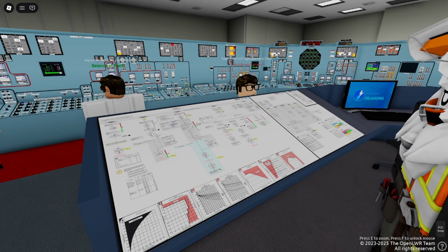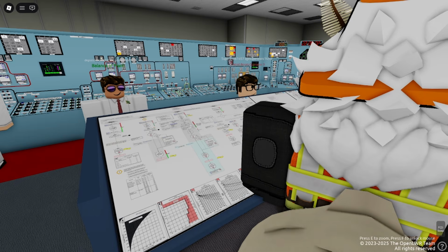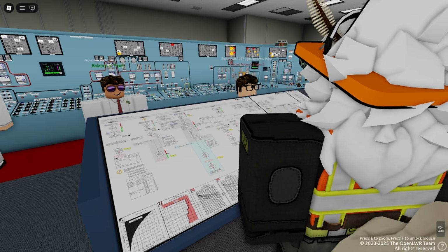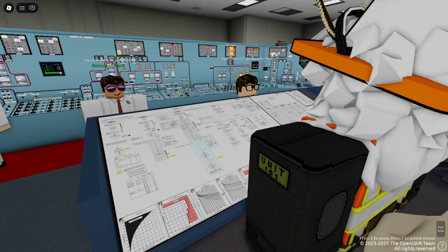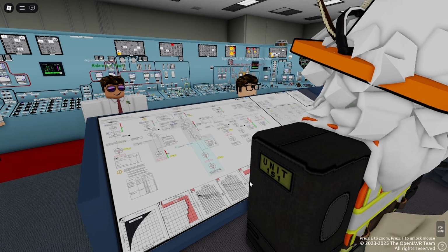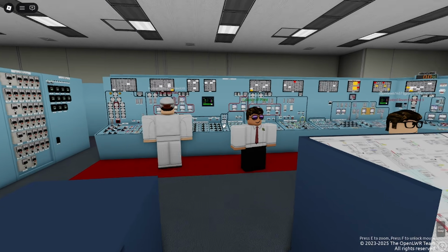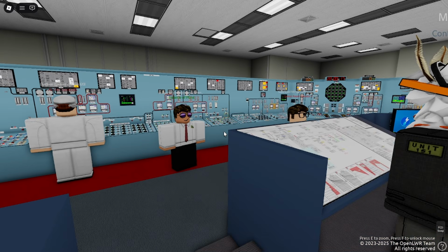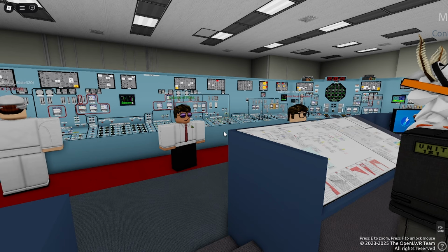That's correct. BOP? Yes. I would like you to further depressurize the RPV fully using SRVs following the depressurization rate of 50 pounds per minute. Completely depressurize the RPV using SRVs and do not exceed a rate of 50 pounds per minute.